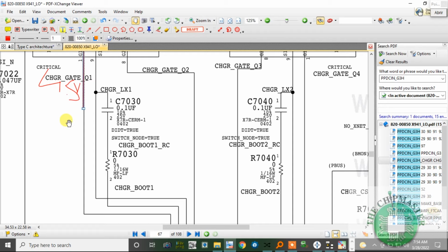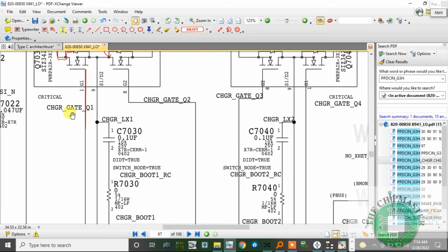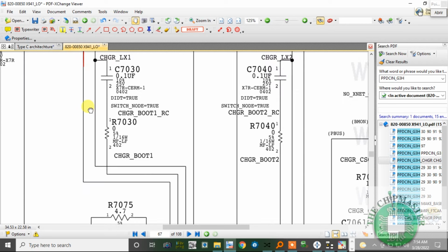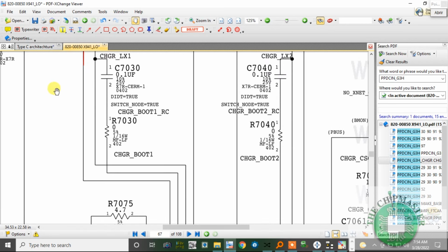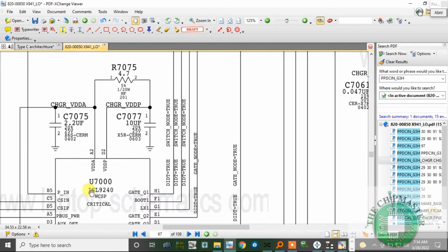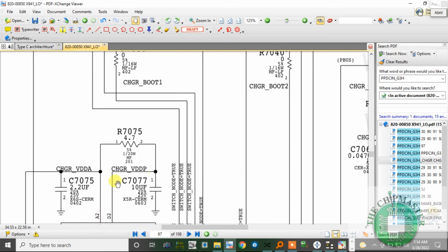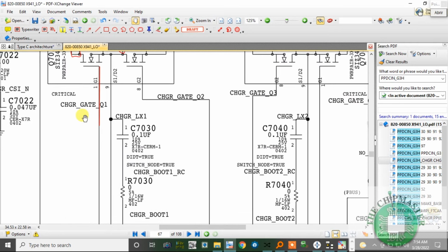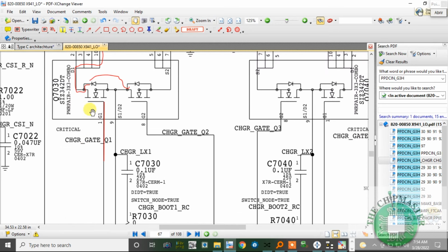I've measured here. So this voltage, minimum voltage, as you can see, it will boost it up to 20 volts, because there's an internal charge pump inside that will boost this voltage to 20 volts, up to 25 volts.